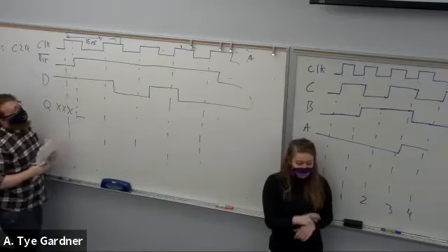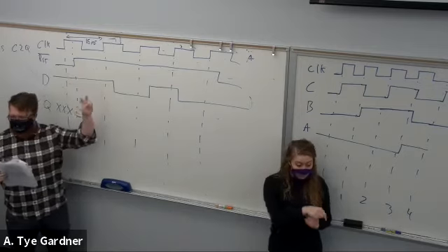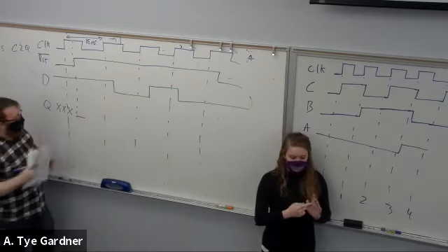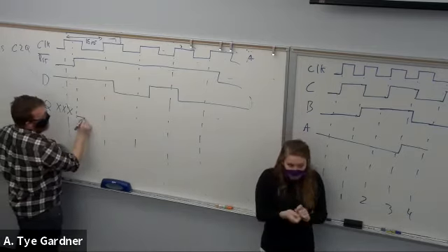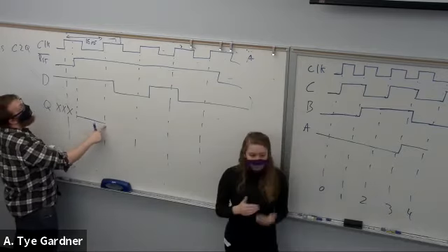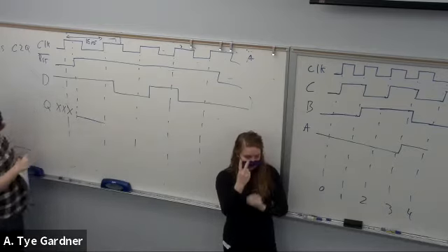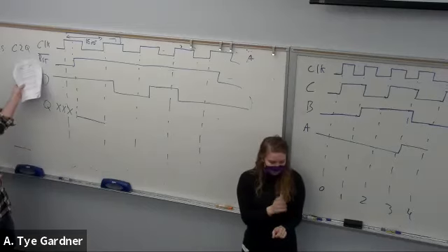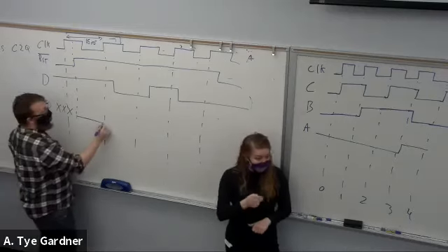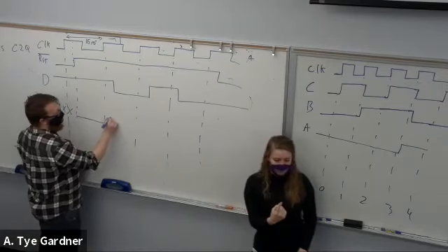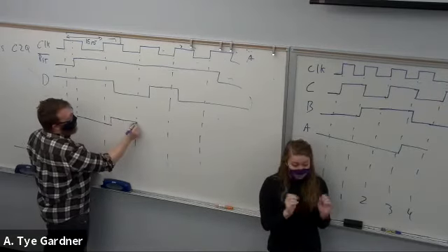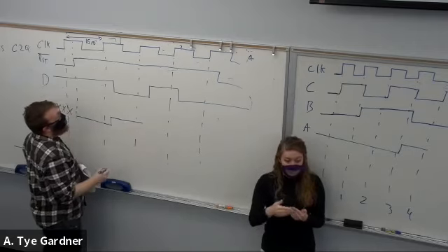Now, this is why I go ahead and I mark out points of interest, where things might actually change. I know that nothing can happen until this next clock, clock number 2. All right, what happens there? Well, we're no longer resetting and data is high. We go to 1 after 4 nanoseconds. And once again, nothing can change till the next clock plus 4 nanoseconds.